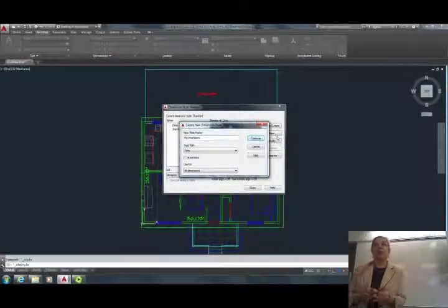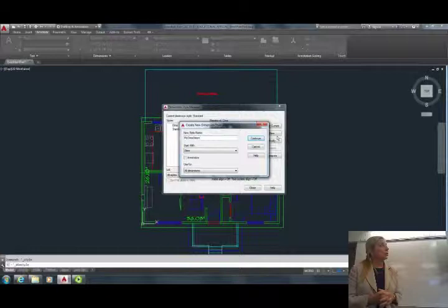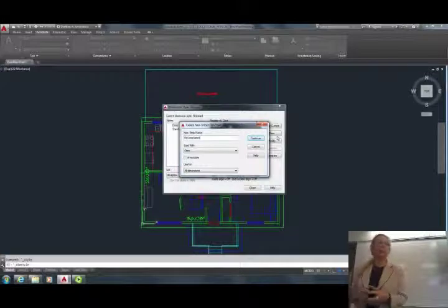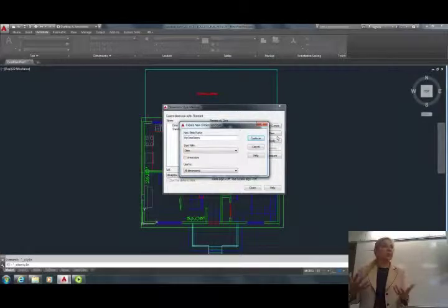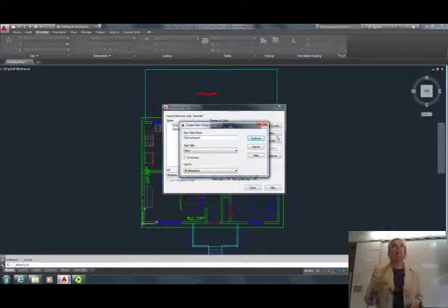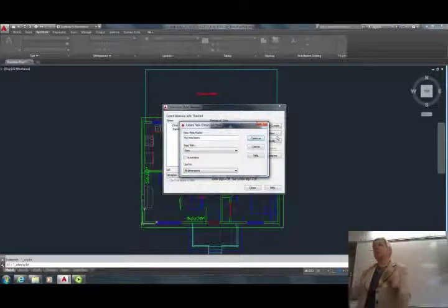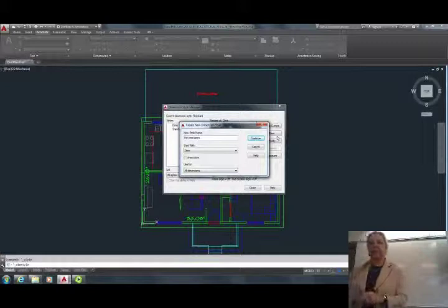So having one good setup for residential is going to go a long way in helping you out with future projects. If you started a template file for your home computer and you already have a standard residential title block, and you started from the architectural sheet sets imperial template, now you could potentially add to it a dimension style and have it already ready there for the next time you do a residential project. Now, having said that, I don't use the management functions. I always forget where they are, and I'll tell you what I do.